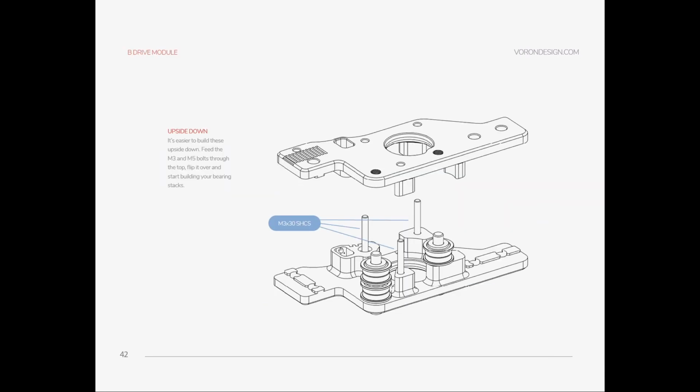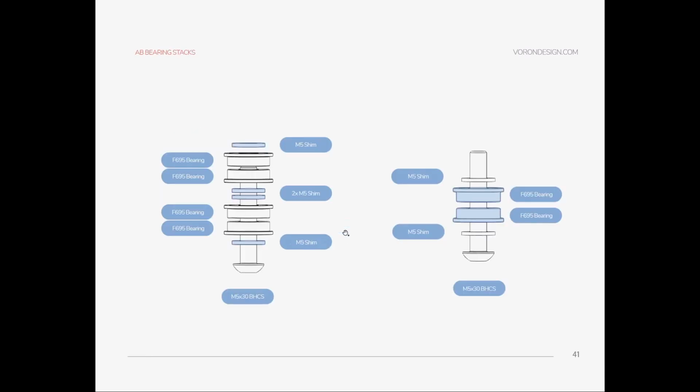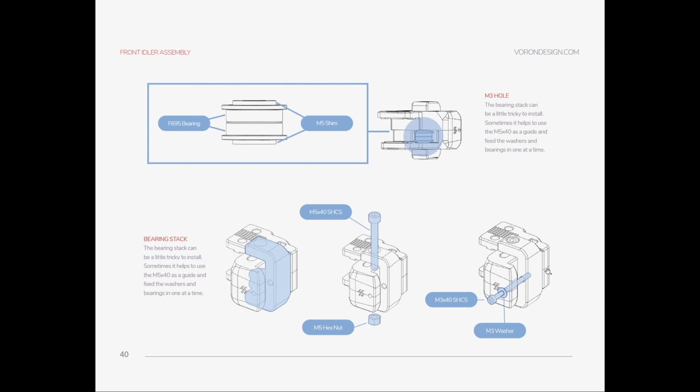And nothing special in here also. This arm is movable, so with that you are tensioning your AB belts. So again, like in the Z idlers, determine a position and try to keep the position the same for both. You will have two for this. So try to keep the position of this arm the same as these two. It will help you tension the belt.